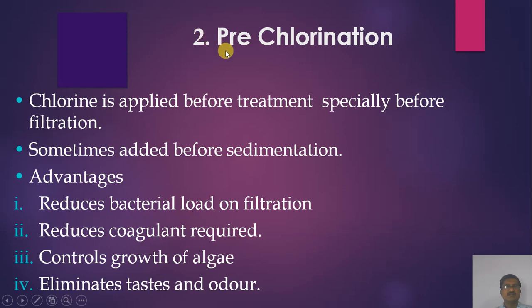Then second is pre-chlorination. Chlorine is applied before treatment, especially before filtration, sometimes added before sedimentation. Advantages: reduces bacterial load of filtration, reduces coagulant required, controls growth of algae, and eliminates taste and odors.